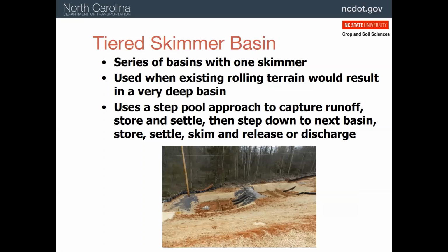When the terrain is very steep, installing a large basin would create a very high bank at the uphill side. So instead, we install a series of basins that are connected to each other. Runoff enters the upper basin, as you see here, often through a pipe or a low spot, and then the water goes through the fabric, through the baffles, as you see here, and then it crosses over into the lower chamber.